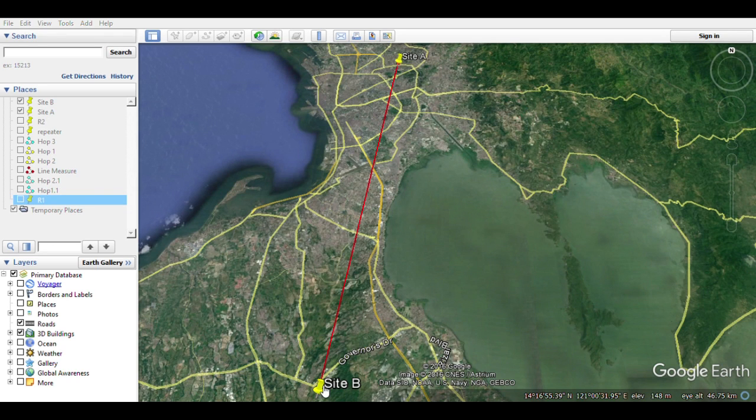You can now click on the first location, then click on the second location. After you do that, a red line will appear. To know the total distance of the path, you can click on the Measurements tab and you will see the distance covered of the path. If you are satisfied with the path that you made, click OK. Once the path is drawn, you can right-click on the name of the path or the line of the path, then select Show Elevation Profile.